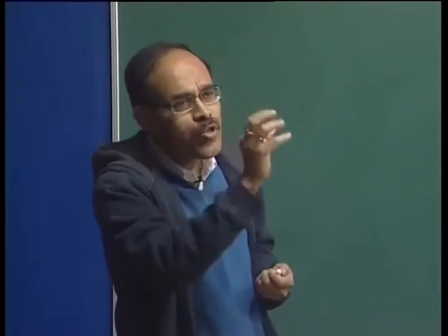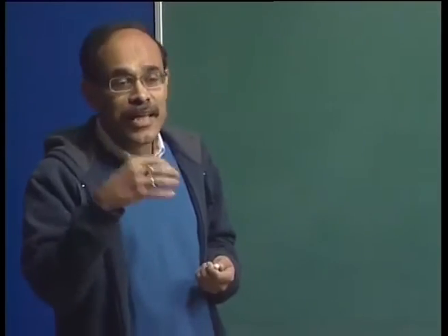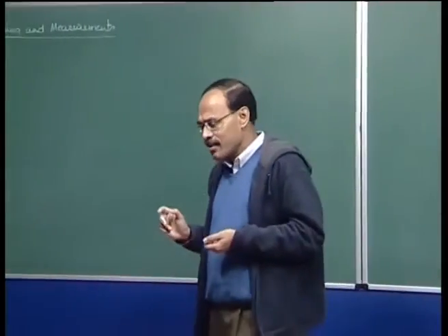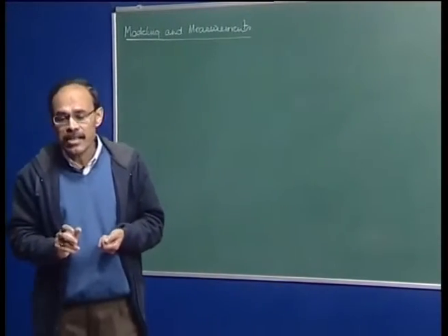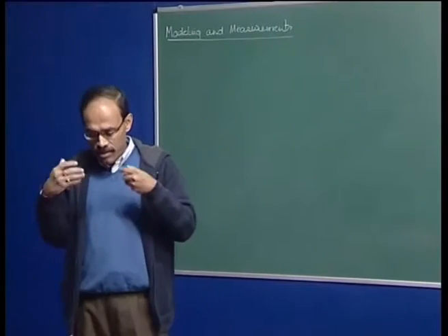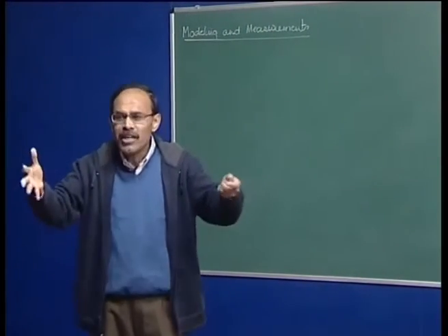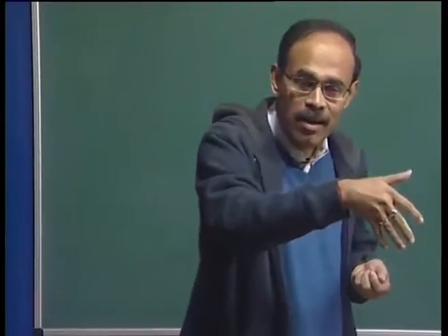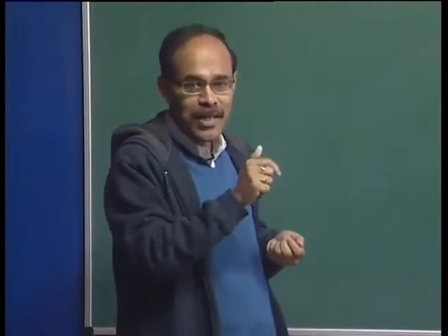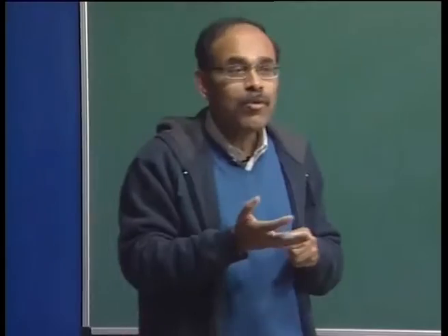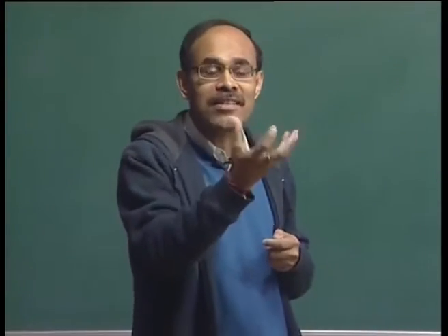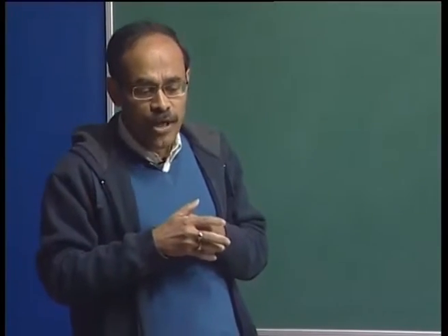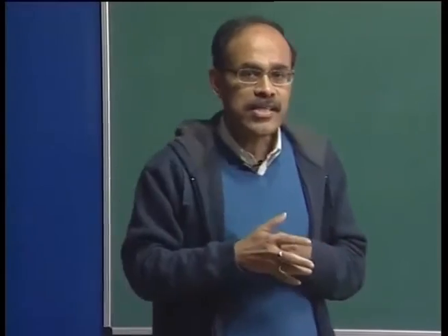Now, if you want to study all these phenomena, like flow of molten steel, inclusion flotation, temperature distribution or heat flow, direct observation is not going to be easy. Those of you who have visited a steel plant, you look at a ladle filled with 300 tons of molten steel. How difficult it is to approach that ladle, immerse a sensor and then record something. If you want to measure temperature, it is not so easy a job, primarily because the environment is extremely rugged. Molten steel is bubbling, boiling, at 1600 degrees centigrade, and it is an extremely hazardous environment. So, direct observation in steel making systems is extremely cumbersome.